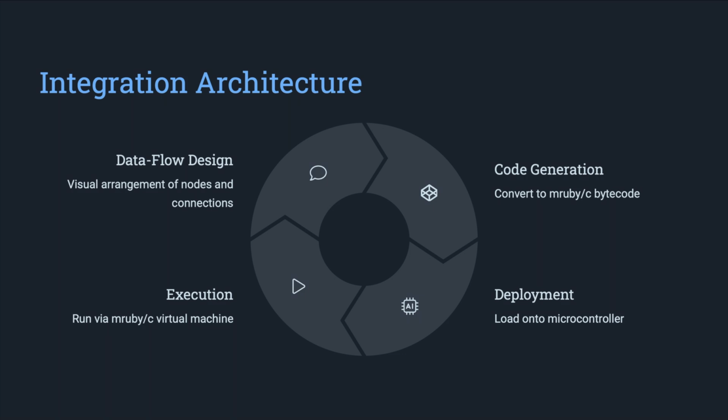Right. Flow 1. A timer node set for 1-second intervals. It connects to a flip-flop node, which just toggles its output each time it gets triggered. That connects to the node that controls the green LED. Makes sense. Blink green every second. Flow 2. Another timer node, but set for 2.5-second intervals. Connects to its own flip-flop node, which connects to the node controlling the red LED. Okay, blink red every 2.5 seconds.